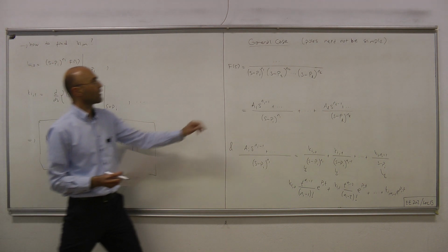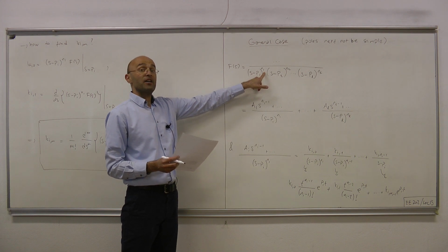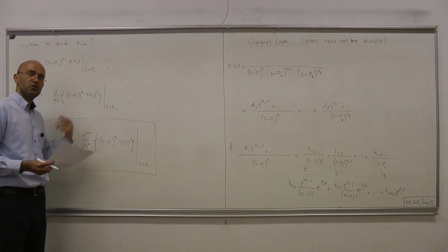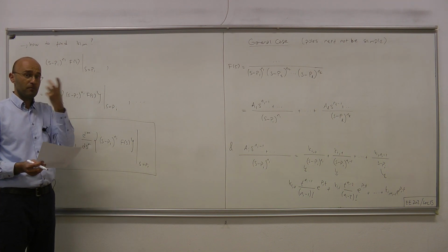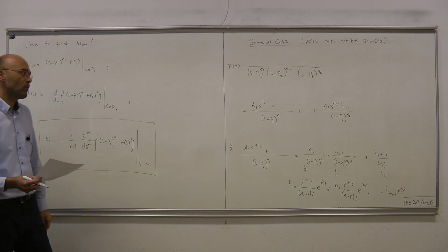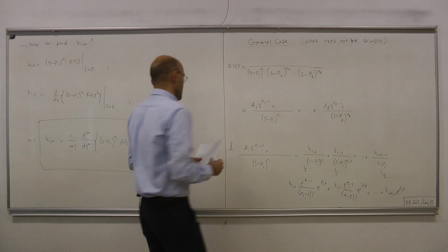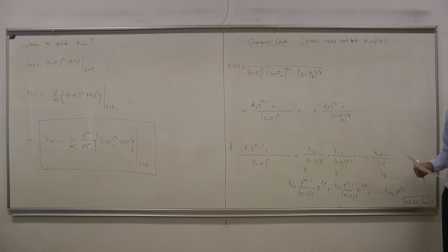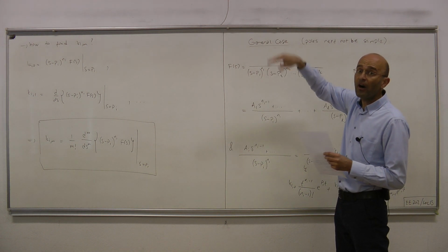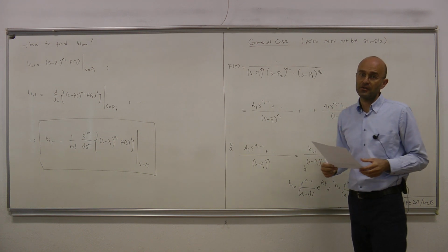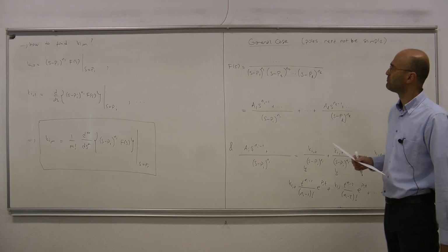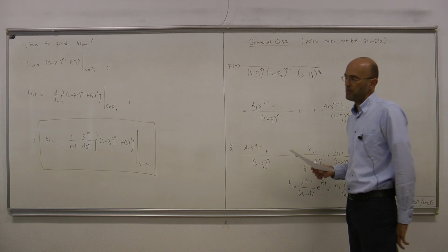Okay. If ni is 1, that means that pole is simple, then this formula immediately boils down to our formula, our identity that we obtained for the all simple pole case. Okay. Now, the notation looks a little bit complicated, but as we said, we're now covering the entire class of signals that we're interested in. Therefore, it's not that surprising that it's complicated. Now, let's apply this methodology to an example where we have some repeated poles.